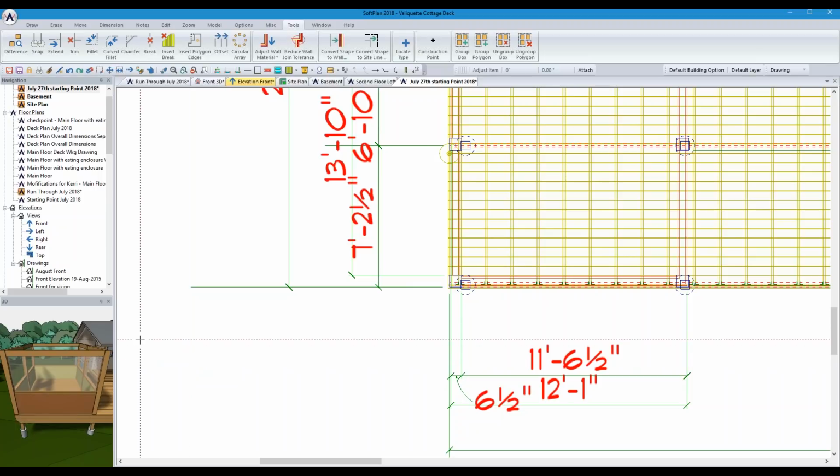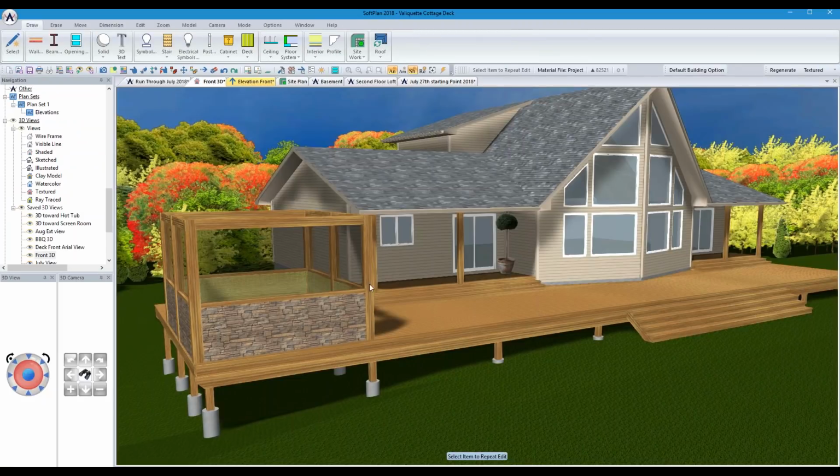The wall joint tolerance basically is like a radar off the end of the wall. It looks for another wall to connect to, and if it finds one, they connect up. It's trying to be smart. In this case, we don't want it to, so you kind of have to dumb them down, make them a little bit more nearsighted so they can't see those posts or see the other wall on the other side of the post. All right, so let's take a quick look at our 3D.